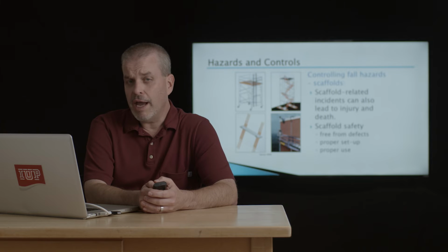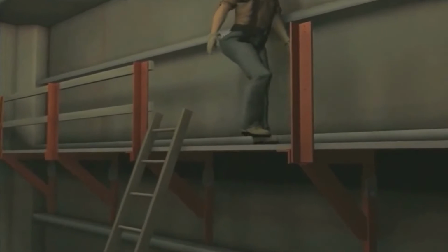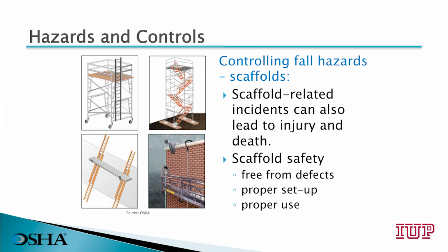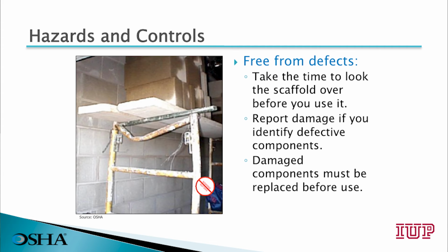How to control fall hazards when using scaffolds. It's important to remember that scaffold-related incidents can also lead to injury or death. So scaffold safety includes making sure your equipment is free from any defects and is assembled and disassembled properly. When inspecting scaffolds, take the time to look over the scaffold before you use it. Report damage if you identify any defective components. Damaged components must be replaced before you use the scaffold.